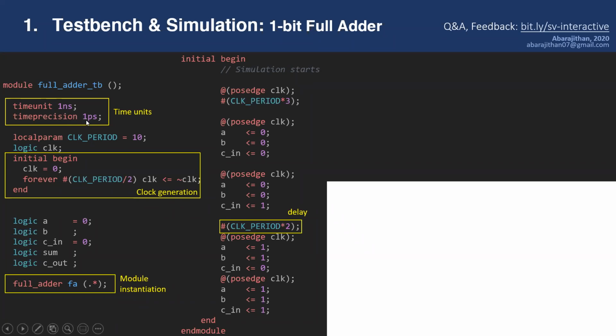These are default values, you can just use them. Changing this doesn't make the simulation run fast or slow, because the simulators are optimized and simulate only at particular points, not for every picosecond, which would take too long. They run the code until something happens, simulate that, then simulate the next event.